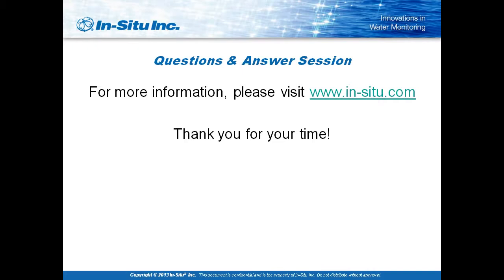Okay. The first question that is posed is, is it necessary to use a gauge transducer to calculate barometric efficiency in a confined aquifer? And the answer there is no, it is not necessary, but it is advisable. Bear in mind what I said about an absolute sensor. An absolute sensor can virtually be used for all pressure measurements. However, you always have to subtract that barometric component before you start looking at the data. So a gauge basically has already processed that because it's already canceled it out.